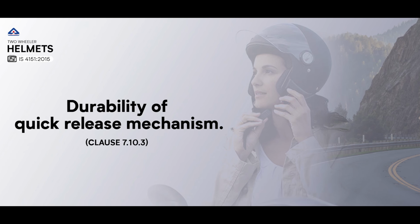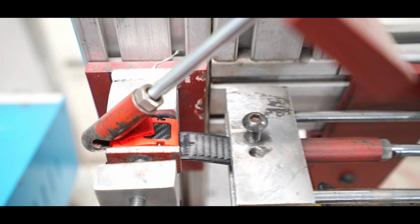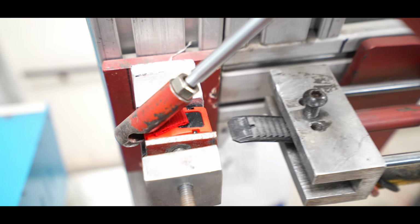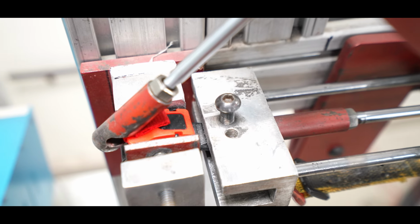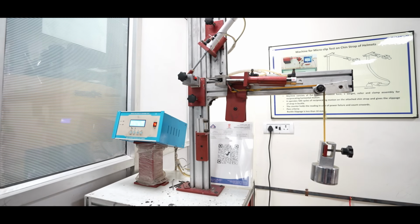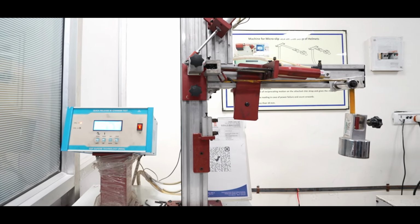Durability of quick release mechanism, Clause 7.10.3. In the durability test, it is checked whether the quick release mechanism is capable of operation after 5,000 cycles are done on the sample under loading of 20 newtons.